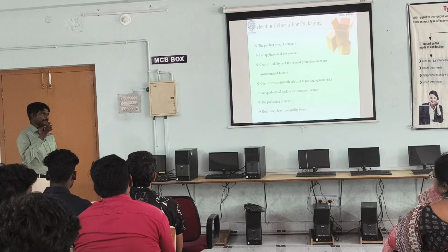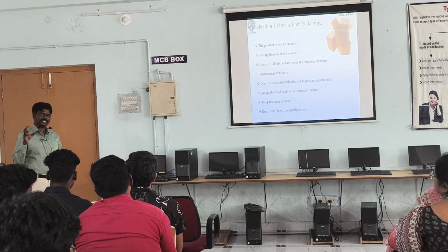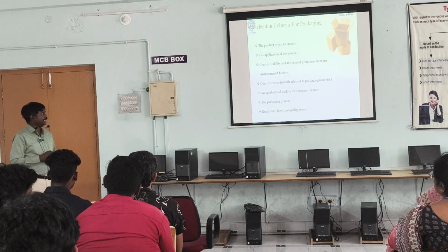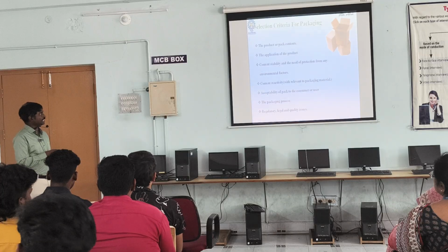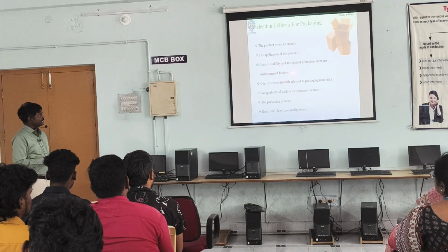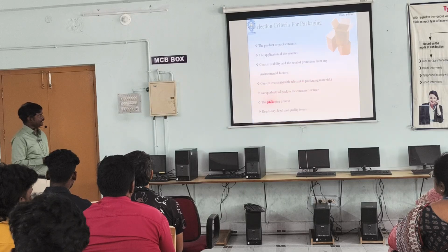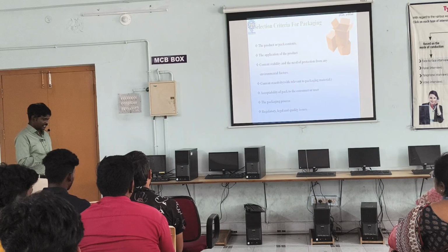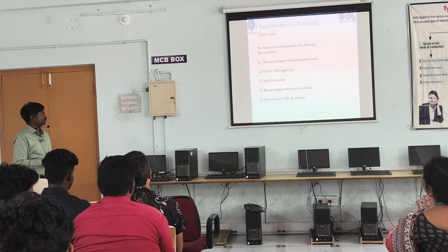And for oil packaging we are using nylon, several layers of packaging material. Like that we will select the packaging, based on the application property, content stability, reactivity, acceptability as per the consumer, and packaging process and regulatory quality issues.